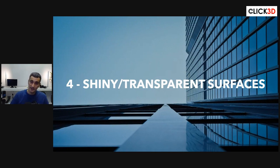On the photogrammetry side, we suffer from the same problem, but for different reasons. So we're not emitting any laser light or anything like that, but we have to worry about index of refraction and stuff. What happens is, in photogrammetry, you're looking for matching textures and you're matching pixels from one image to another. And as a result, if I have a reflective surface, as I move around that reflective surface, I get bright spots, I get reflections, and so the reflection is moving. So if I'm trying to match something that should be fixed in one photo and the next photo, and it just keeps moving around all over the place, I've got a problem.